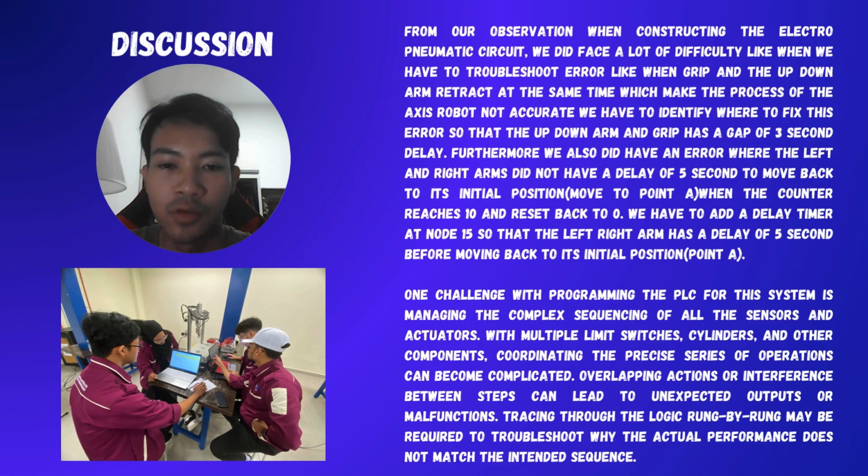Okay, for the discussion of our group, from our observation when constructing the electro-pneumatic circuit, we did face a lot of difficulty, like when we had to troubleshoot errors, such as when the grip and the up-down arm retracted at the same time, which made the process of the assist robot not accurate. We had to identify where to fix this error so that the up-down arm and grip have a gap of 3-second delay. Furthermore, we also had an error where the left-right arm did not have a delay of 5 seconds before moving back to its initial position, which is point A.